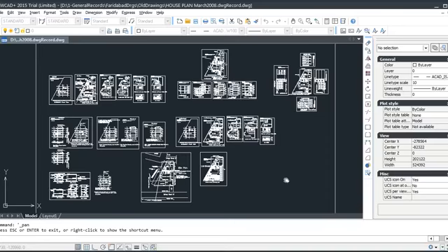Then we have to see, when we backfill, we have to backfill in layers of 150 mm thick, the final one 200 mm, and that's also tested. People don't do it, I know, they don't want to do it. They just fill everything by excavator, put water on that. They think it will be done automatically, but nothing is automatic in this world.